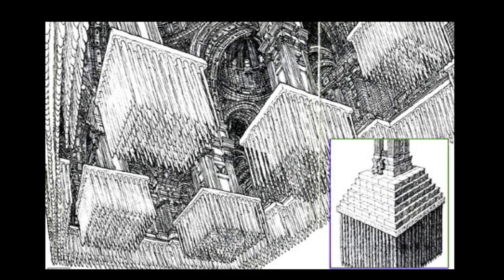And so basically, what the Venetians did was to design buildings that, generally speaking, are going to be point load structures if they're extremely large. And then they're going to connect the piers with relatively thin walls. Now, for smaller structures, it was completely different, right? Smaller structures, you would have load-bearing walls, but smaller structures wouldn't need the enormous areas of pilings. If you're having a large vaulted structure like some of the churches or some of the enormous palaces in Venice, then it just makes more sense to concentrate the location of the foundations and therefore the location of the pilings into a point load system.